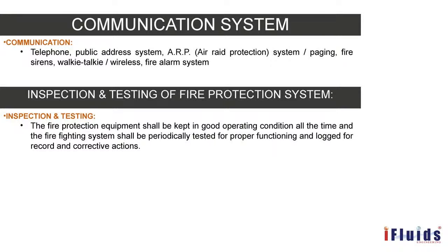If it is a fire water spray system, then it also has to be tested periodically, once in 6 months. For storage tanks and for LPG spheres and bullets, it has to be tested once in 3 months if the drill system and all those things are there.